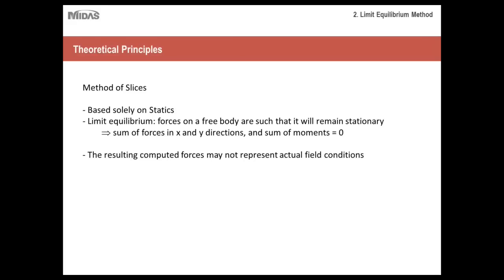That's another important thing to keep in mind. If, for example, you check the forces acting on those slices, just keep in mind that there are various assumptions made when doing the limit equilibrium method, which would lead to forces that may seem erroneously high or erroneously low. Those don't actually represent actual forces in the field.